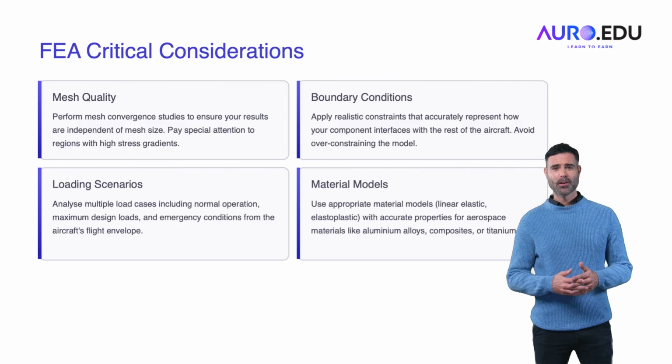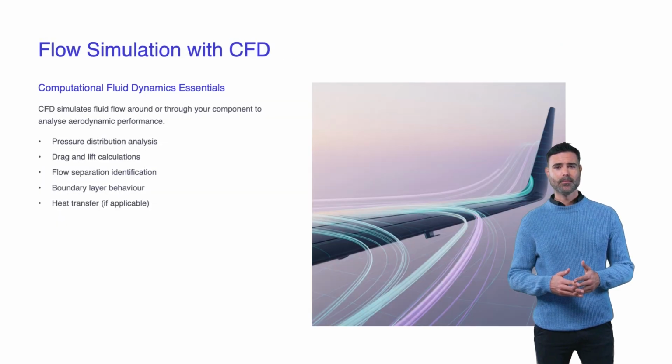FEA, critical considerations. Mesh quality is key. Too coarse, and results are inaccurate. Too fine, and simulations are slow. You'll need to balance realism and efficiency. Boundary conditions must reflect how the component connects to the aircraft. Don't over-constrain. Loading scenarios should include everyday use and extreme cases. Use accurate material models for your analysis.